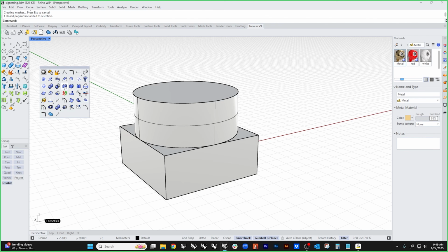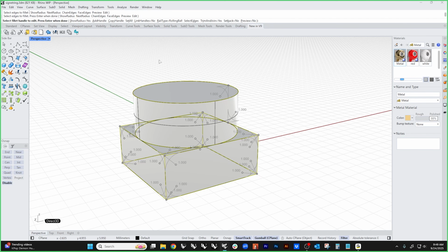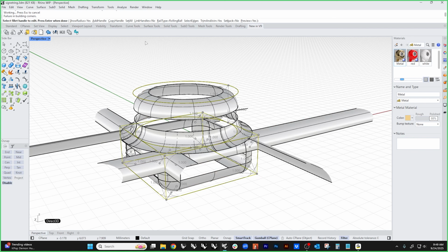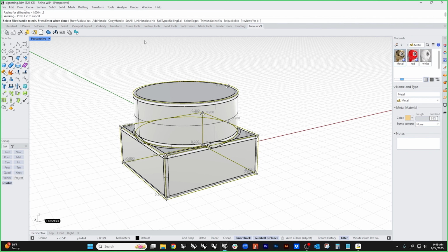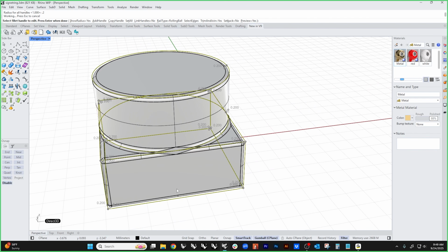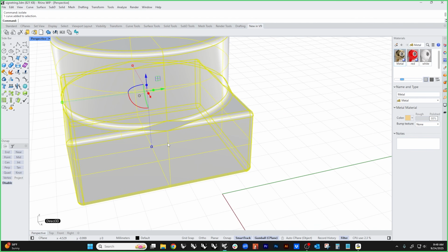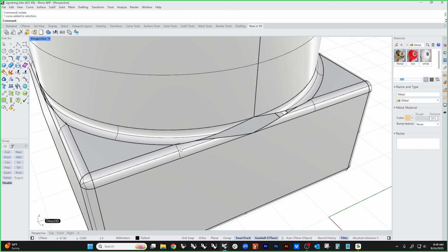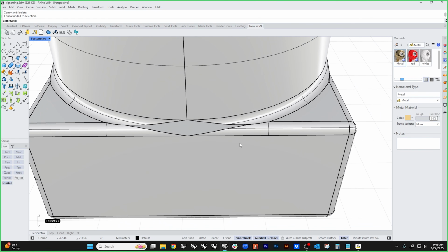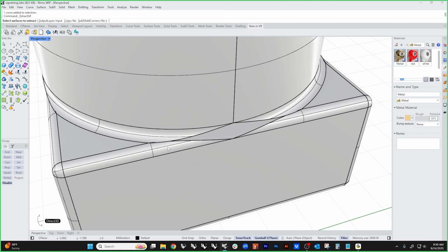If we do an edge blend on this and we preview this, and let's get a size that works, you'll notice that it completes this everywhere except it opens up this weird little hole. And this is a common failure in Rhino kind of style fillets. And so what we can do is come and pull this out. This used to be a nightmare to try and model around. And if we split this by isocurve at the end there, and we make this a little less awful hole.